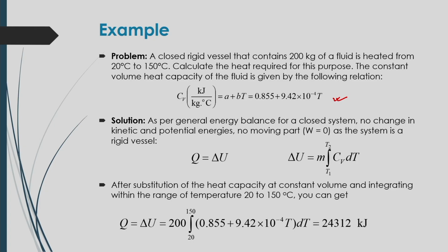As per the general energy balance for a closed system, in this case there is no change in kinetic energy, there is no change in potential energy, and also there is no moving part there. So, in that case we can say that there will be no shaft work done on this system, and as the system is a rigid vessel, we can say that mass is constant there. So, according to that we can write this